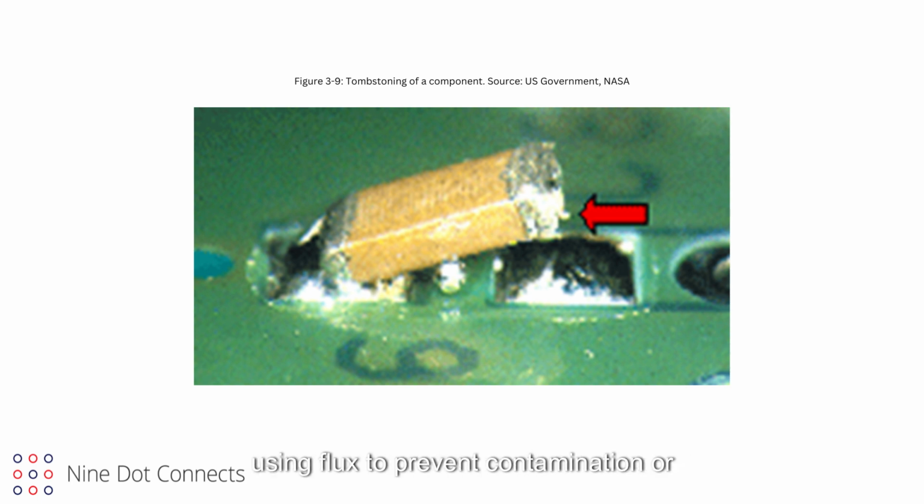In addition to using flux, to prevent contamination or oxidation, the solder paste can be cured in a nitrogen atmosphere. Nitrogen boxes are commonly found in both fabrication and assembly facilities. The idea behind the use of such boxes is to lessen the other gases that may be present in the box, by constantly feeding nitrogen gas into it. Whereas oxygen is reactive to materials, nitrogen is inert.